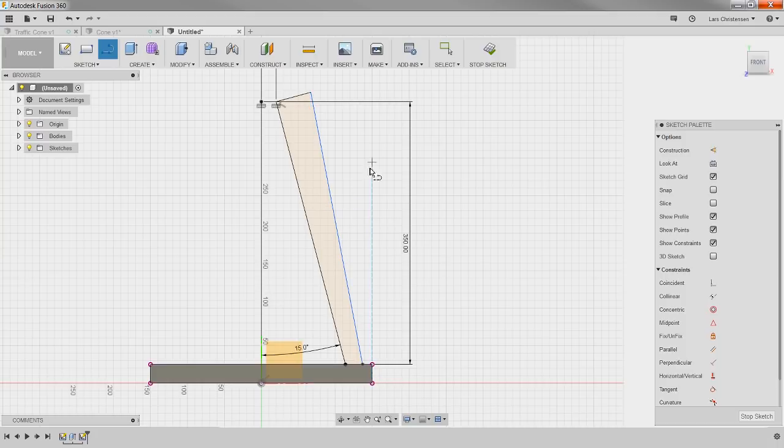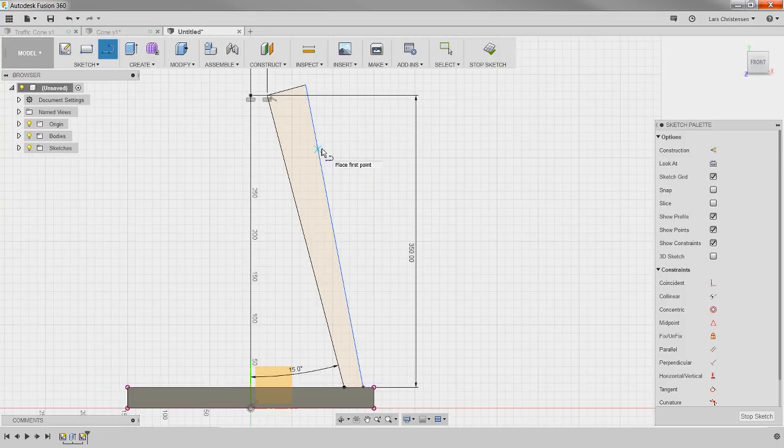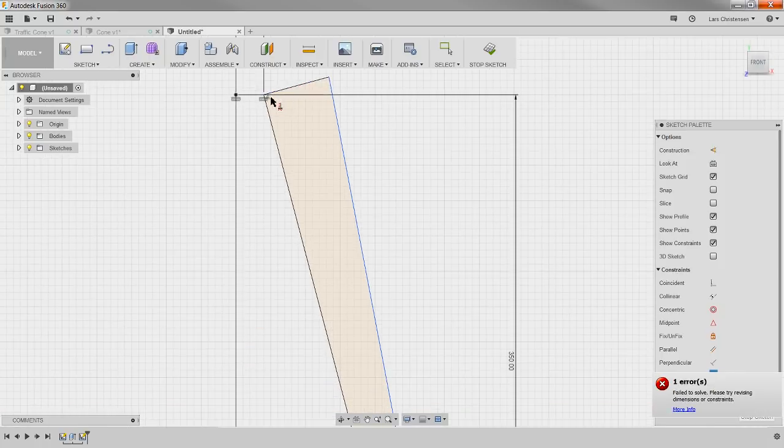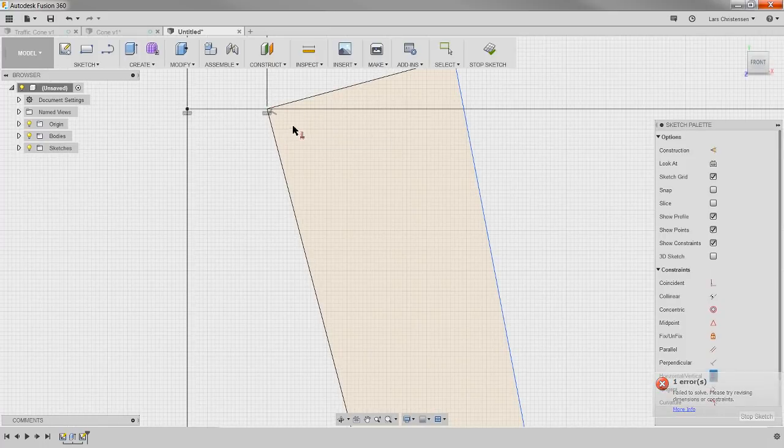But you will see that again, we have blue. We got to make this black. So we're going to go back, I'm going to X out of the line command there. We're going to go back to our constraints, and we can start adding constraints. So one is maybe going back to the horizontal. Instead of selecting two endpoints like we did before, you can select a line, and that will not happen because I actually got another constraint. When I drew that up, I didn't want it.